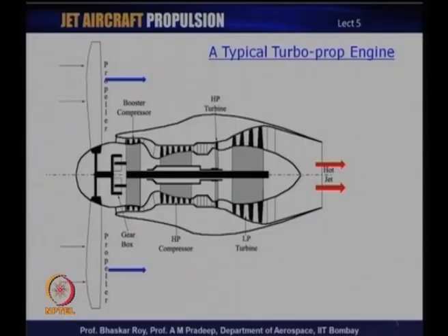Okay, so, let us start off with what can be called a basic turboprop engine. A typical turboprop engine essentially is run by a basic jet engine. The basic jet engine has the capacity to produce more power than is required to run the compressor. This turbine, which is now capable of producing so much power, as you can see in this particular diagram, has a very large number of turbine stages in the second group, which can also be called the low pressure turbine group.